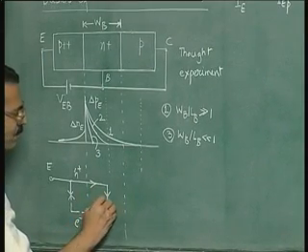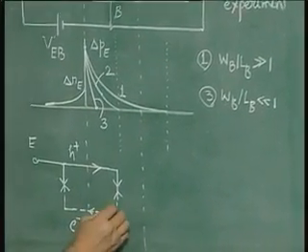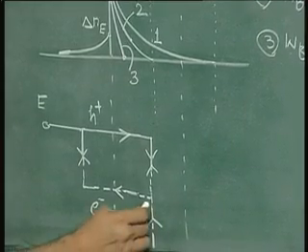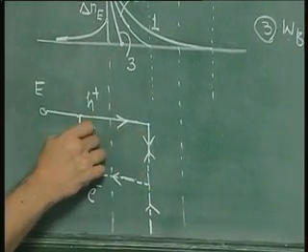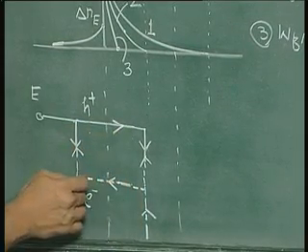So obviously they recombine with electrons which are supplied from the base contact. So the base clearly is supplying electrons to recombine with the holes injected from the emitter, and it is also supplying electrons to be injected into the emitter.